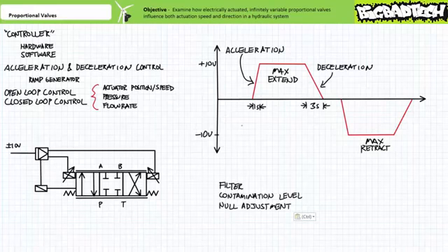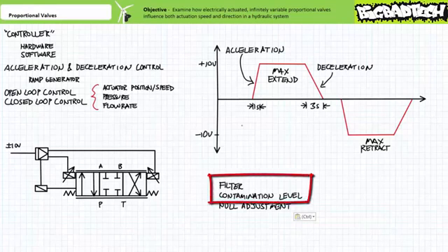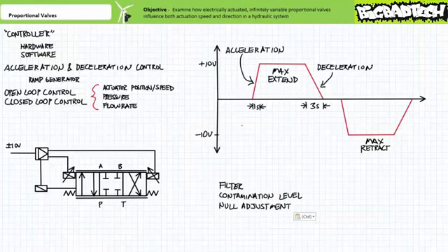Moving on. Proportional valves are fussy, picky, finicky, persnickety beasts as fragile as an origami butterfly made out of a $1,000 bill and must be treated as such. Good filtration and proper fluid selection is essential to the proper operation and reliability of a proportional valve, and as such, systems incorporating proportional valves often necessitate stringent contamination levels and inline or pressure filters upstream of the proportional valve to protect their fragile inner workings. Additionally, some proportional valves go to the trouble of including small built-in filters. Failure to properly filter fluid or using cheaper, i.e. dirtier fluid will result in progressive loss of functionality.